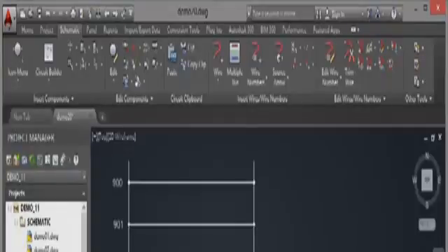When we inserted our ladder into our drawing, which by the way is still Demo 20 in the project Demo 11 for working file purposes, we used a setting when we inserted the ladder. So let's go and have a quick look at that. Let's revisit that. So if I come up here to the Insert Wires Wire Numbers panel in the Schematic tab on the ribbon there, if I go to Insert Ladder, it was 4.5 inches, the default width. That's the default width in the drawing properties and more than likely the project properties because I haven't changed it individually for any drawing or any project. So that we know the width there is 4.5 inches, so I'll just cancel that for the moment.